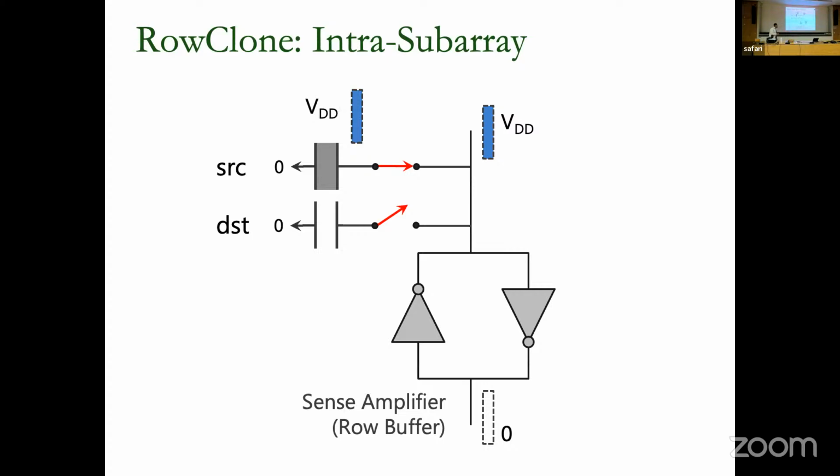In this case here, VDD. So if I want to do a regular access to the destination row, next I would send a pre-charge to put this bit line back to VDD over 2, but I'm not going to do that. I'm just going to simply send activate to the destination row, and since this sense amplifier's voltage level is higher than the voltage level inside the capacitor, the data is going to be copied to the destination row itself, enabling us to do this DRAM row copy.